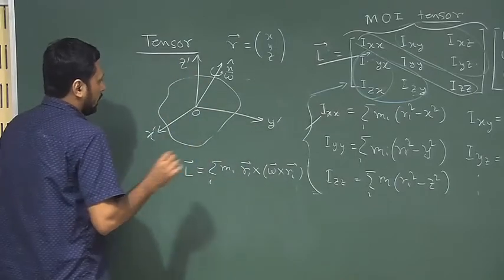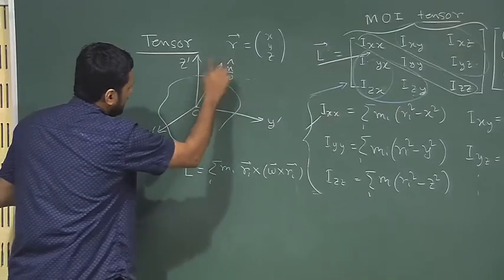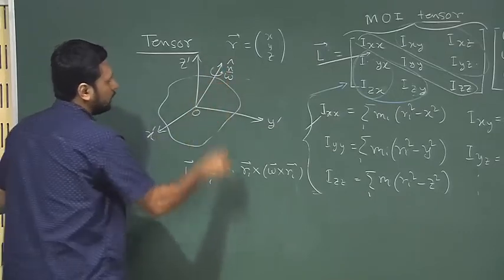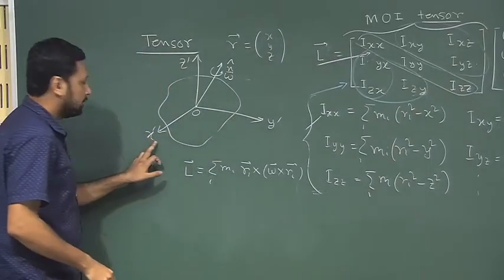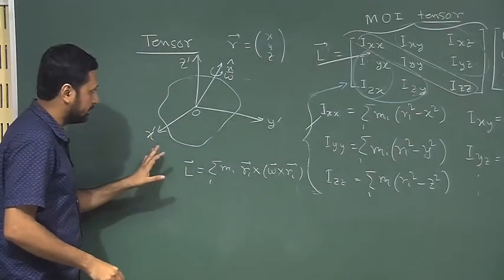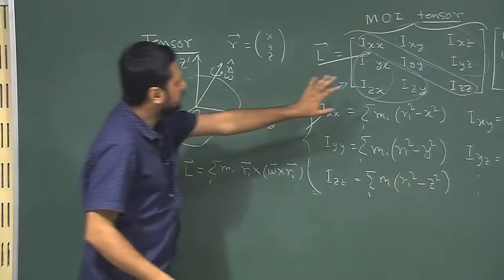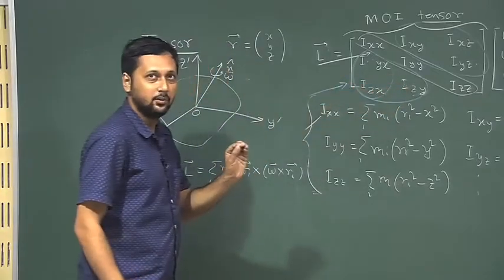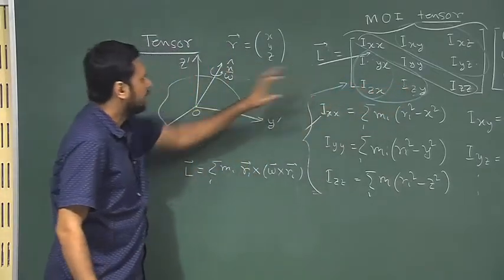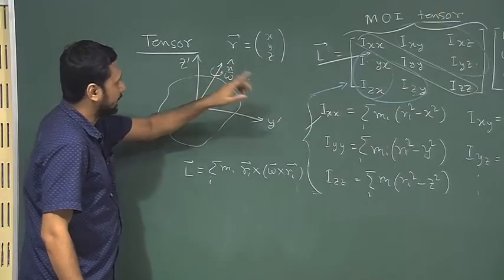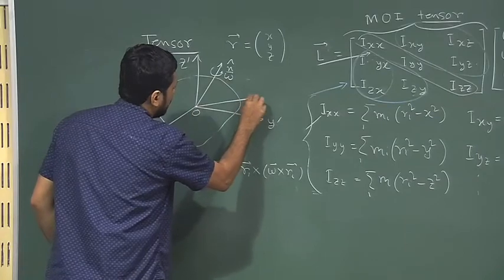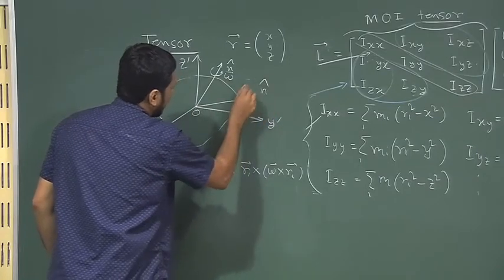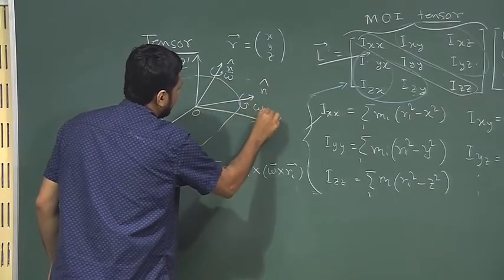Now, for any arbitrary rotation omega, we can always decompose omega x, omega y and omega z in terms of the space set of axis system, and if we know this tensor, I can exactly tell you what will be the value of L, or what will be the direction of L vector for this value of omega. You change your axis here, and you have another value of omega.